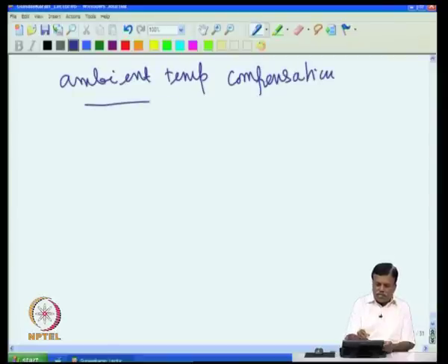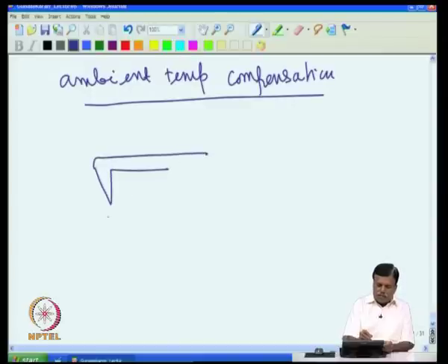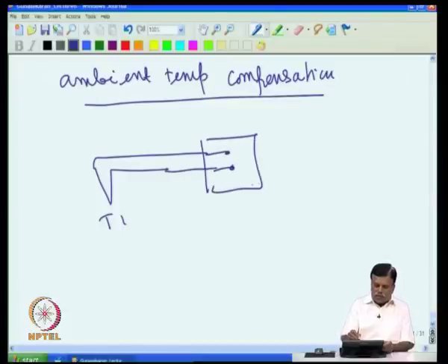So, what is done in this case is that you take the junction, keep it wherever the temperature is to be measured, say T, and then the thermocouple is terminated in an isothermal block, say copper, with of course insulation so that it cannot get shorted. So, this is at T ambient.